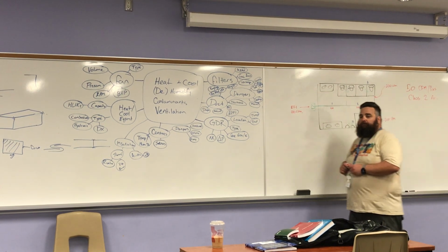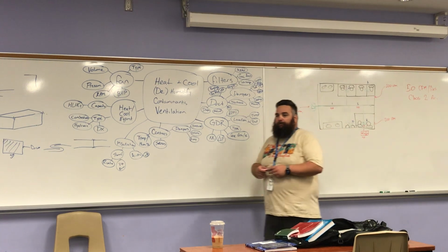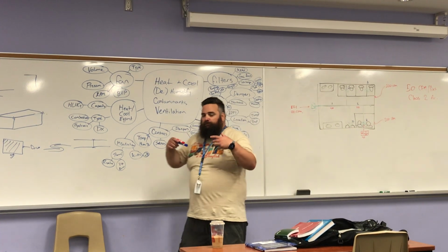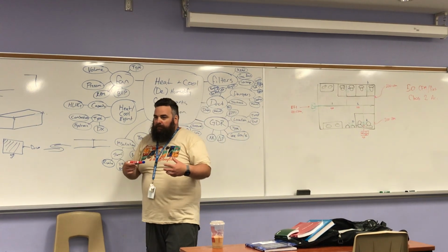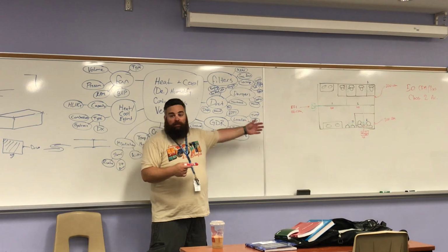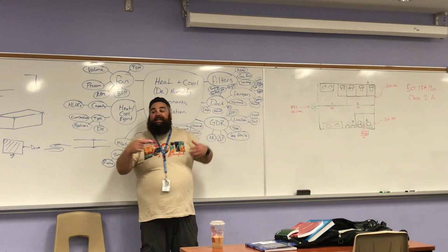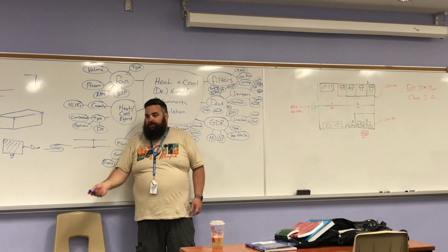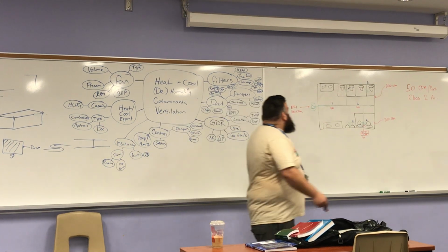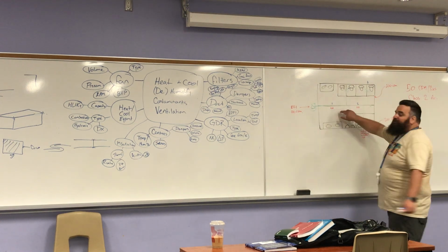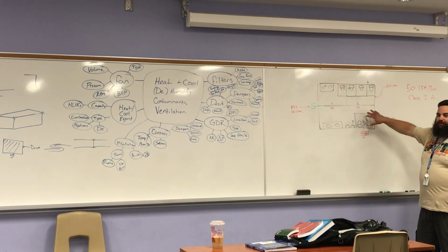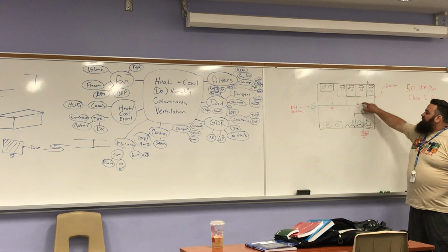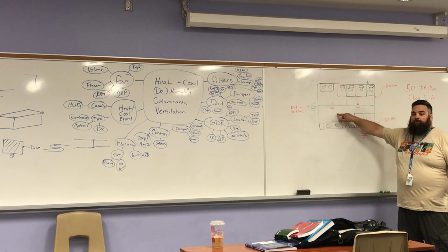You could reduce duct size after. Right? So when we lose mass, in this case when I say mass, we've lost air. Or when we gain mass, because we're exhausting, we gain energy. There's more air, okay? So there's going to be a difference in duct size as a result. This will be smaller, 2 will be smaller than 1.